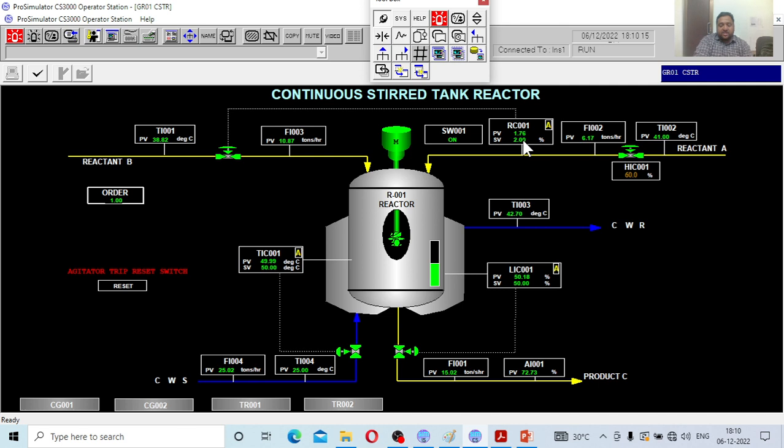See, the process value and set value are different now because I have affected the ratio. Accordingly, it will send a signal to make sure the ratio is 2, that is, process value and set value equal to 2. And what happens inside the reactor? More reactants are put in, so the temperature has risen because it is an exothermic reaction. The more A and B participating in the reaction, the more the temperature is going to rise. Automatically it will send a signal to the valve, and the flow has to be raised. You can see 25.28, 25.29. The cooling water supply to the reactor is getting higher.